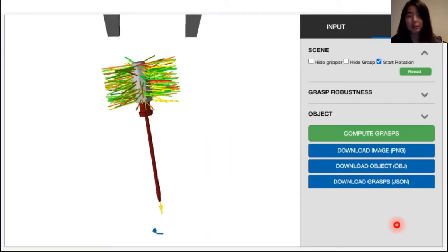After the user clicks on Compute Grasps, in the UI now, we can see the grasps generated. The grasps in the stay-out region are filtered out, and the most robust grasps, represented by the whiskers in green color, are along the direction of the rotation with the torque.